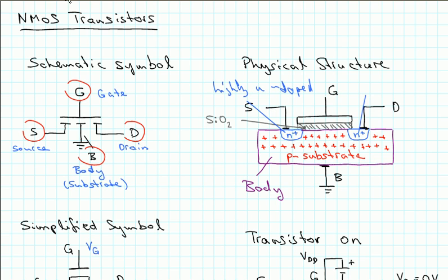And then there is a piece of insulation put here. So this gray piece here, that's insulation. And that's where the oxide in the metal oxide semiconductor field effect transistor comes from. So the O, the oxide, is actually this insulating material here. It's often made from silicon oxide, but it can be other forms of oxide or insulation as well.